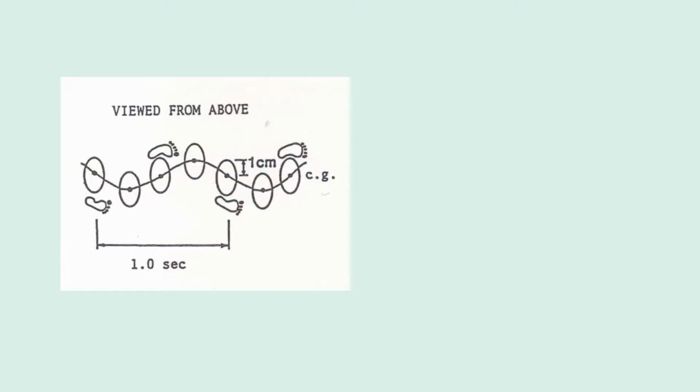When you walk, the center of gravity of your body moves left and right, which induces a lateral force. If you are a fashion model, you walk straight, and this lateral force is small. If you are drunken, you walk left and right, and the lateral force is large. On average, it is about 10% of the vertical force. The pace you walk is 2 steps in 1 second, left and right foot in turn, so the period of this external force is 1 second, or 1 Hz.